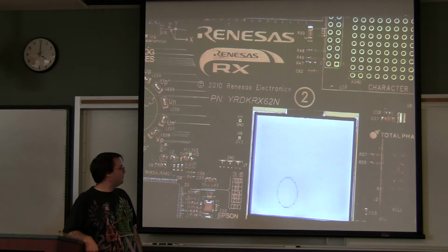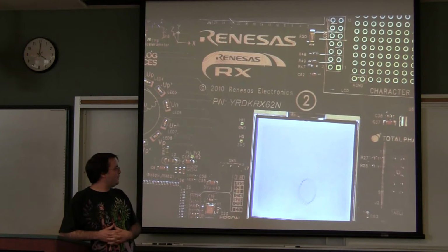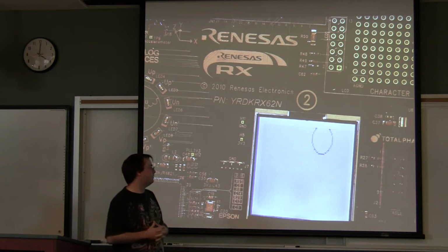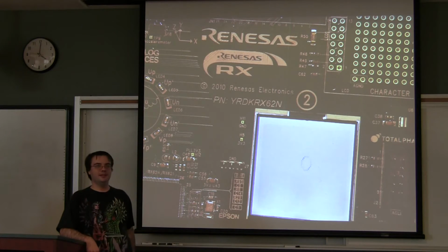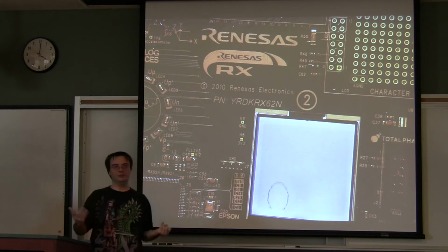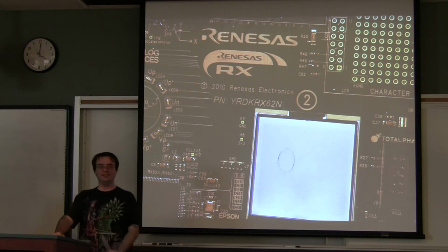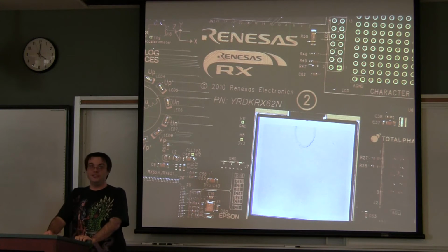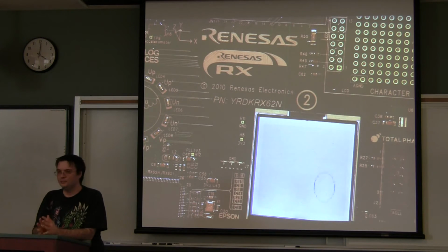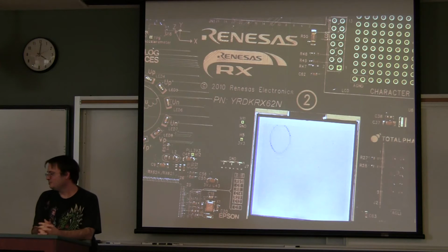So hopefully you learn a lot out of this lab. It'll be somewhat enjoyable. We'll warn you though that we'll be working with floating point numbers in this lab, and you've got to be careful where you define them, because if you put too many on as local variables, you can end up with some weird things happening in your code, which you can see with a debugger, so it's another useful tip for learning how to use the debugger. I recommend global variables for most of the floats for this lab, as a hint. Any questions?